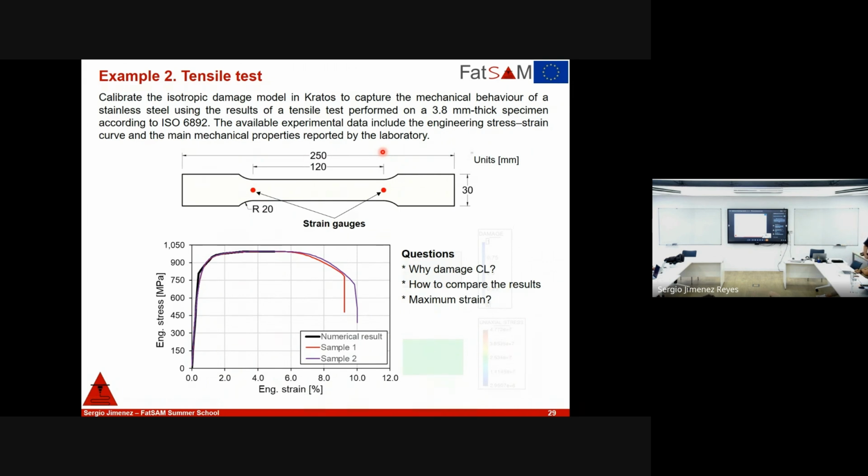What I don't understand right now is assigning a really high fracture energy, what results would that give? It will allow you to run the simulation. If you run 500 joules per meter square, it will tell you this fracture energy that you are providing is not enough to arrive at this point here, to arrive at the second region in which I will be doing this exponential softening.